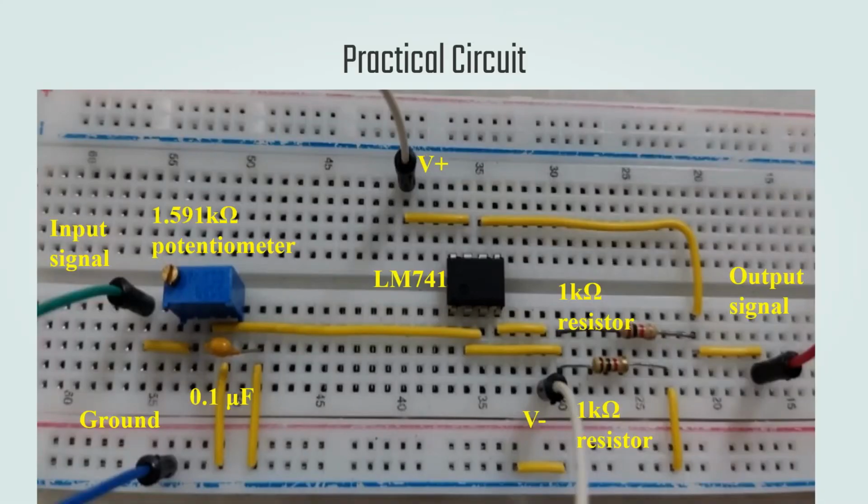The potentiometer is very important in practical cases because it can control the cutoff frequency of the low pass filter, and it has high precision of resistor value and can be adjusted. So we use a potentiometer at the low pass filter side.